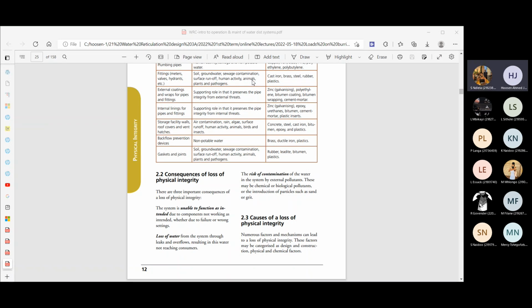Yes, you've got contours, right? You have the layout plan, and you've got contours on the layout plan. So you'll have to interpolate between those contours. You'll measure the distance between the two contours, and then the distance from the one contour to your manhole, and that will help you to interpolate to determine what the level is. Oh, okay, sir. Thank you. Okay, anybody else?